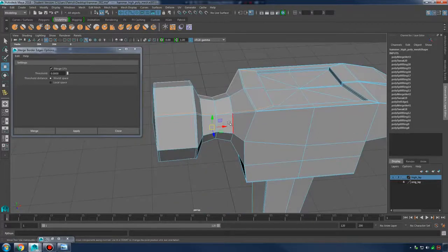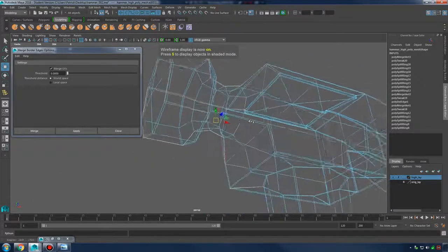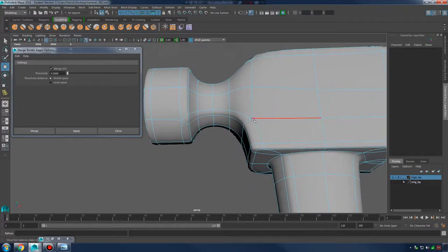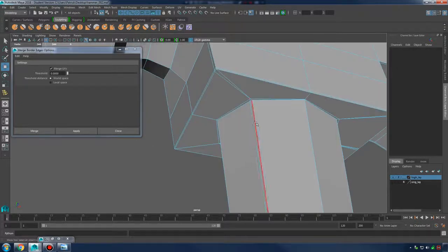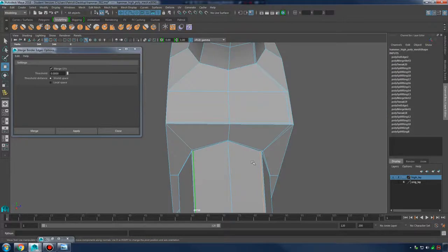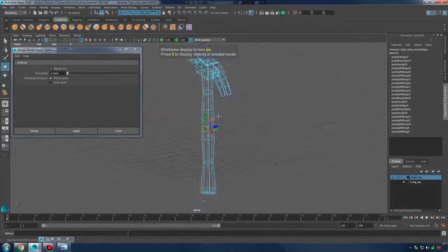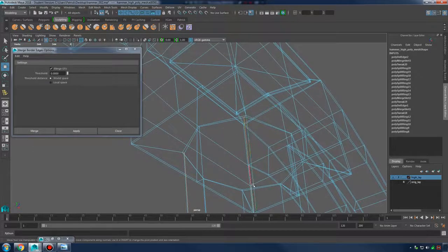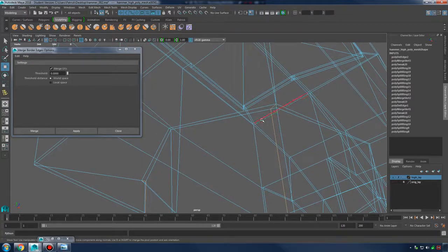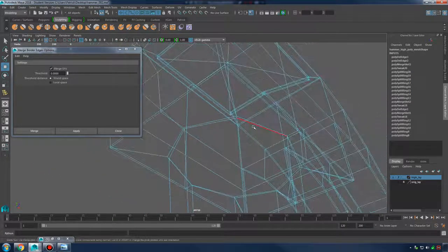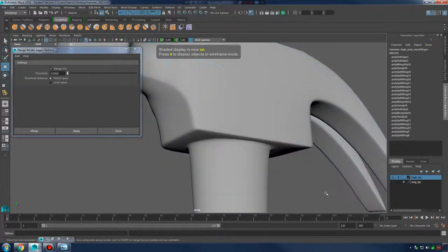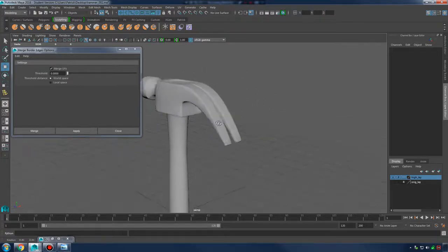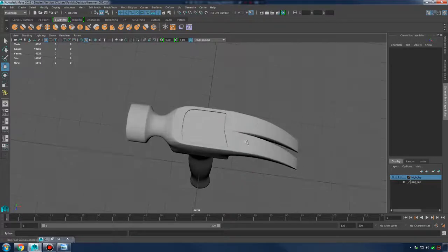So notice how I have this tied edge loop. It's only affecting the top of my hammer here. I'll delete that. We still have our nice hard edge we saw in our source material. Delete this bottom edge loop, and since I tied it off, we're only getting the bottom of our handle. See, since these vertices are tied off and merged here, our edge loop terminates at these poles we're creating. So it allows me just to isolate the edges and delete them where I don't want those hard edges to occur. And it's a little bit of an advanced concept, doing some high poly modeling like that.